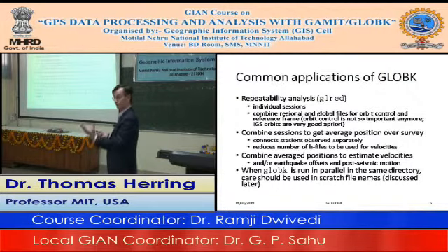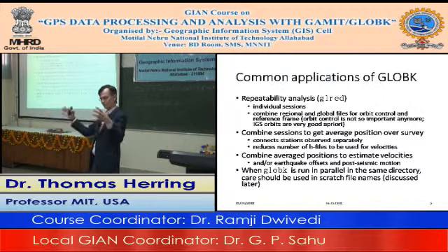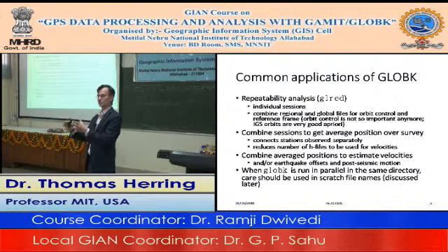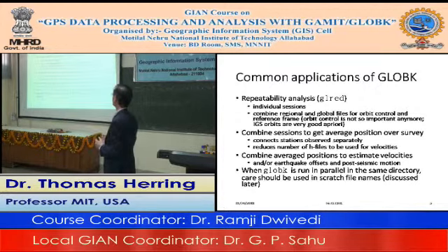So if you do have survey data that spans, say, a couple of weeks where you've gone to different sites, you'll be able to blend them all together to make just a single solution for that survey, which is a useful way to do that type of data. That helps reduce the number of data files that you ultimately use when you do the velocity solutions. The combined average positions you can use to estimate offsets and earthquake offsets and post-seismic motions as well.